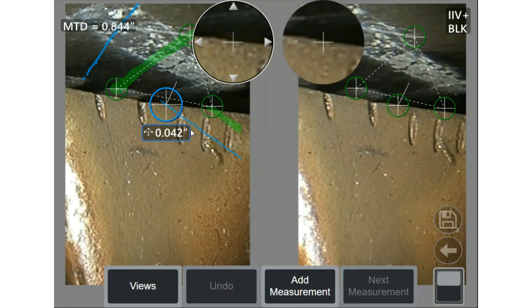And then this blue surface mask is data that is 42 thousandths of an inch perpendicular to that measurement plane. So you see I have disparity here, and it shows up over there. There's definitely something going on here, and you just simply would not know that without a lot of work understanding what's going on with a 2D image.